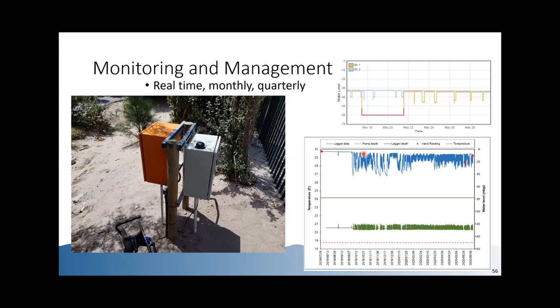So I just want to quickly unpack what this graph is reflecting here. On the x-axis, we've got time series data. We've got about a year of data from this borehole. On the vertical axis, we've got water level drawdown, meters below ground level, and that's indicated by this blue line. When we go to the field, we take a manual reading that's represented by these red stars, diamonds.